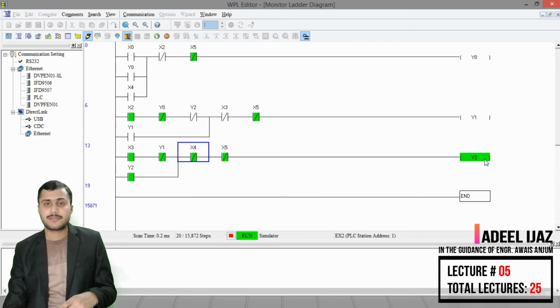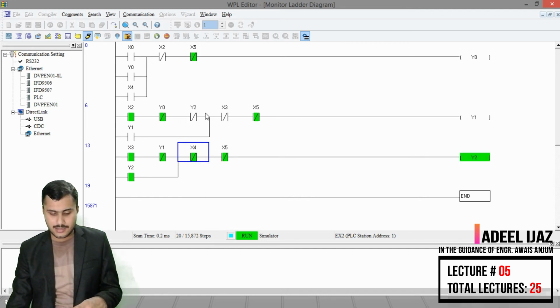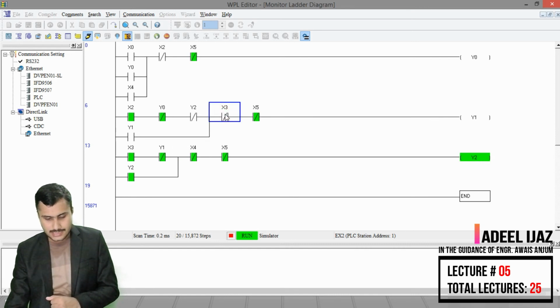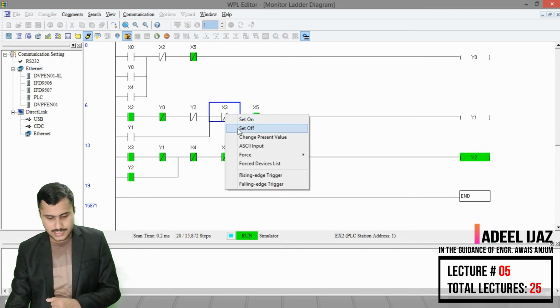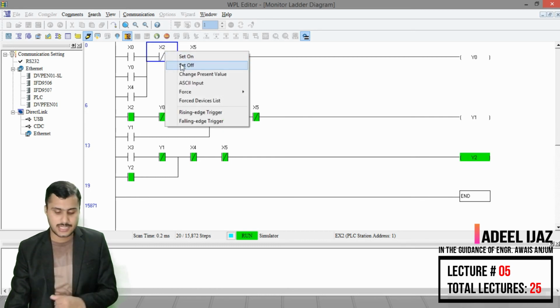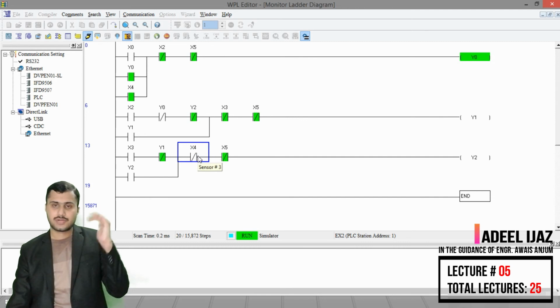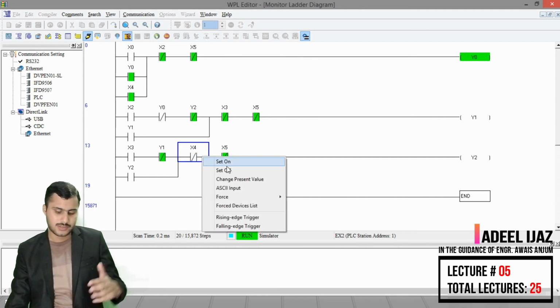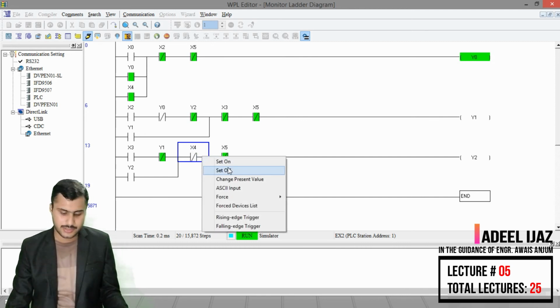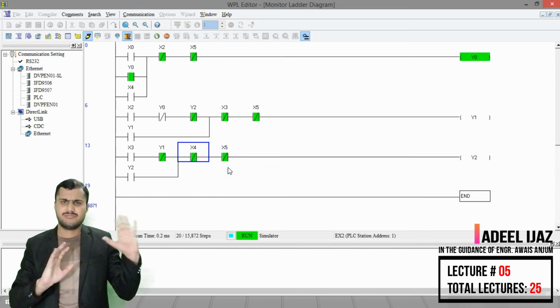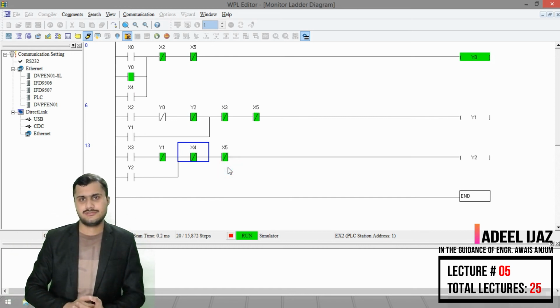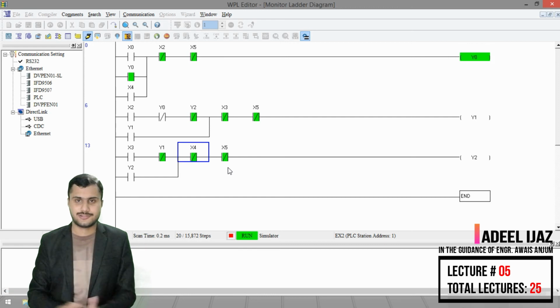So our outlet pipe now gets activated, and the liquid starts to drain out. In that case, our sensor number 1 gets disengaged, our sensor number 2 gets disengaged, and then our X4 is activated. Liquid starts to enter into the tank, X4 will return to its original condition, and thus this process continues till the end of the batch.